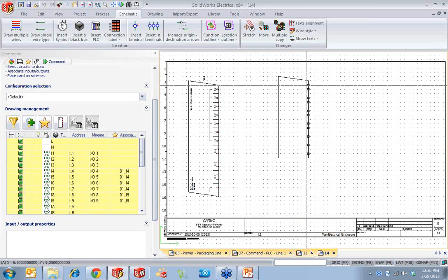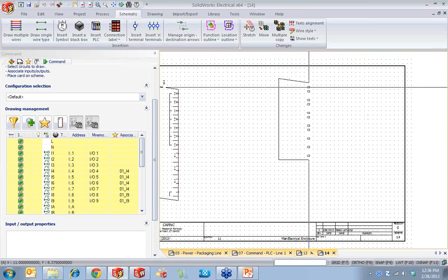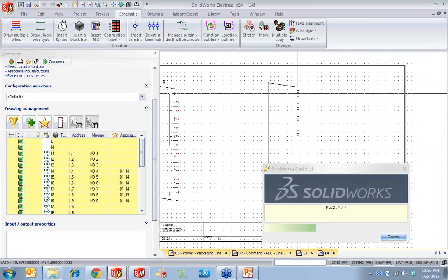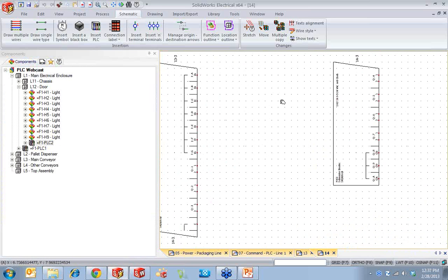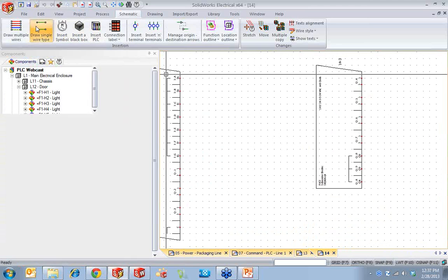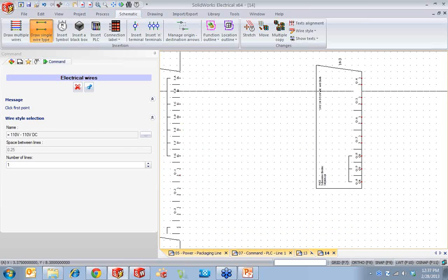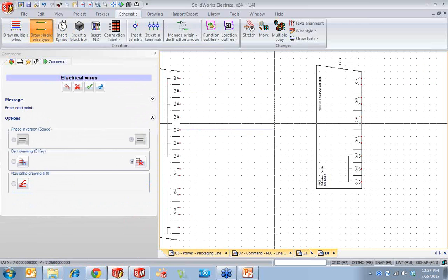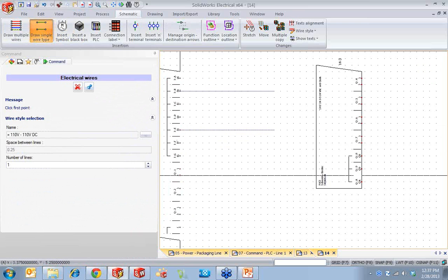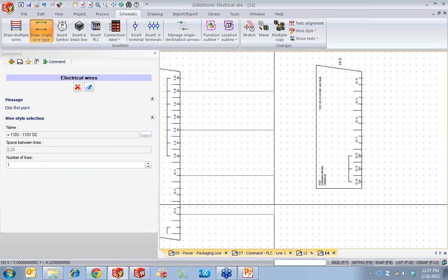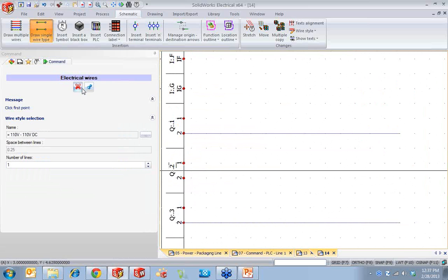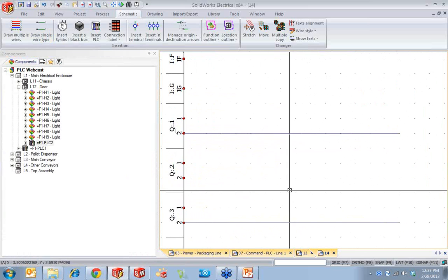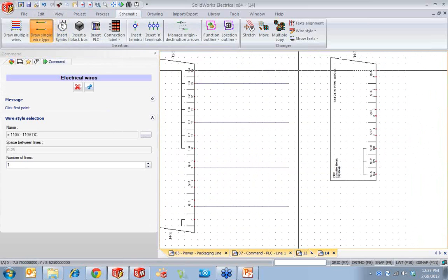I'll have it insert the default, and then that's the end of it right here. Yeah, I can actually put it all in one page like that if I want to. And I didn't have it insert macros in this case, but I'm going to go ahead and draw wires manually because it's not that hard. So there's a wire, and I'll just insert a few like so. And it knows how to trim them against these terminals automatically.